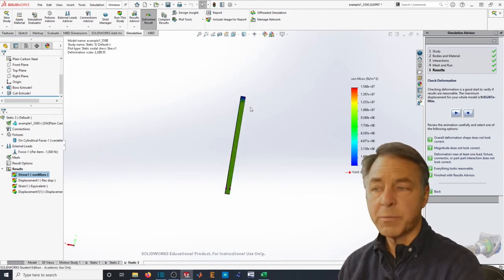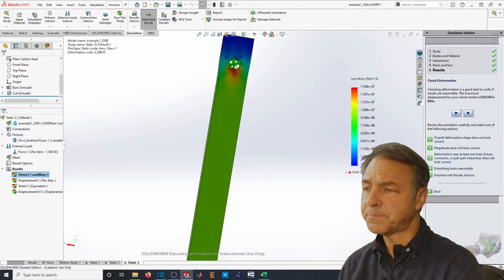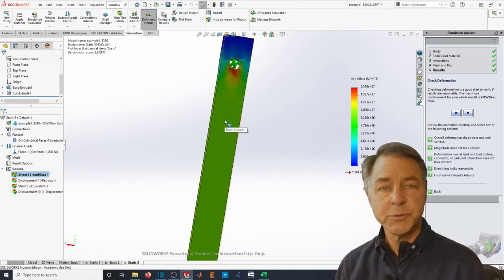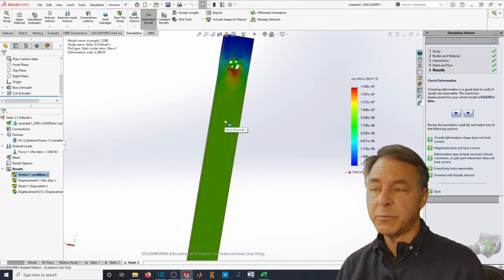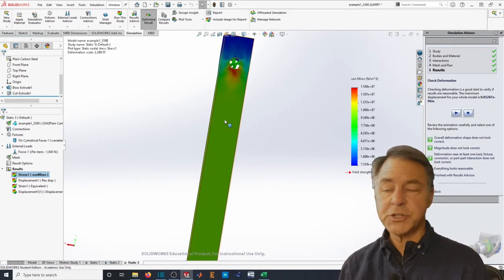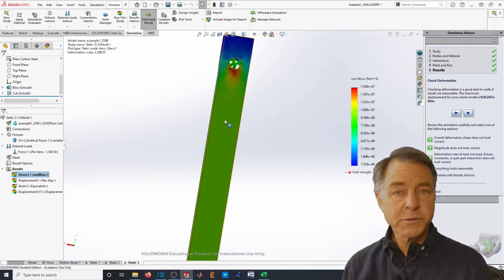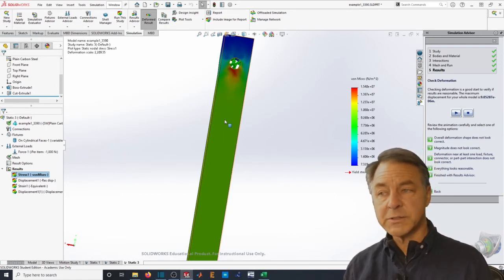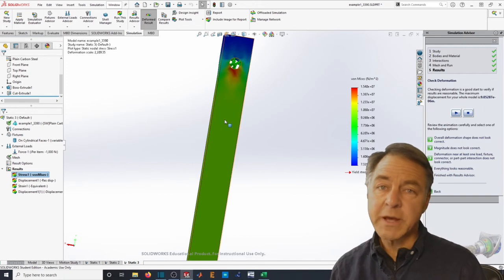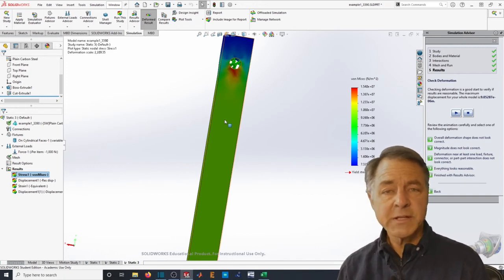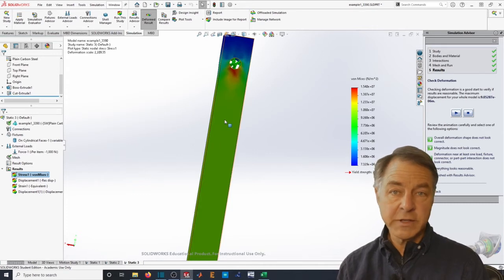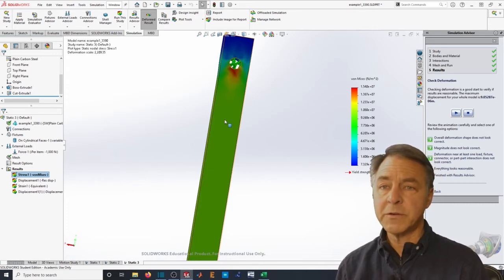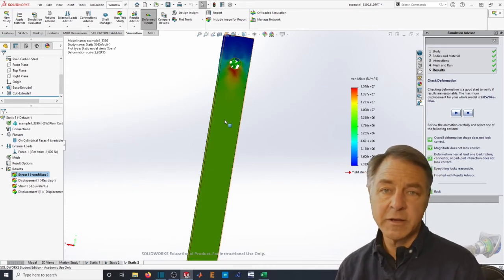Now, the proper thing we should be doing with this is doing a series of runs with different grid sizes, grid geometries, with different hole sizes, hole locations, to just get a sense as to whether or not our model is behaving as one would expect from common sense, and whenever trying to find the validity of the model, to try and take it back to a hand calculation that you're confident in.